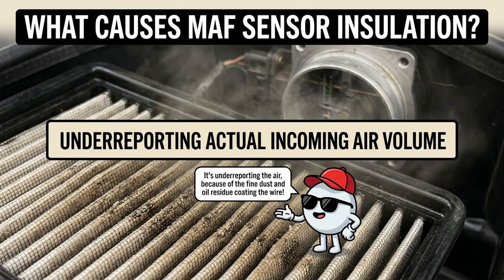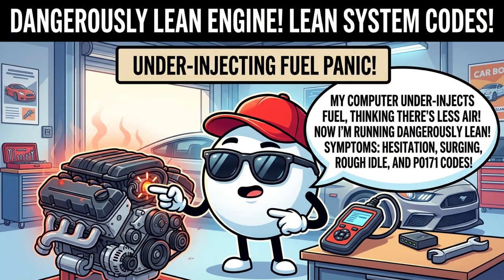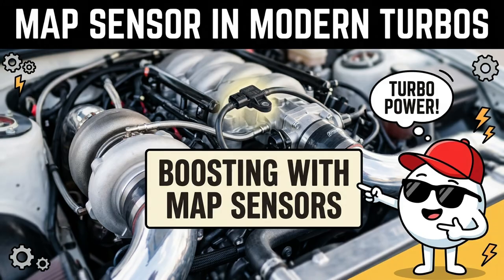When a MAF sensor fails, usually caused by fine road dust or oil residue from cleanable air filters coating the platinum wire, it becomes insulated. It underreports the actual volume of incoming air. Thinking less air is entering, the computer underinjects fuel, forcing the engine to run dangerously lean. Common symptoms include severe hesitation during acceleration, engine surging, rough idling, and system lean diagnostic codes like P0171.